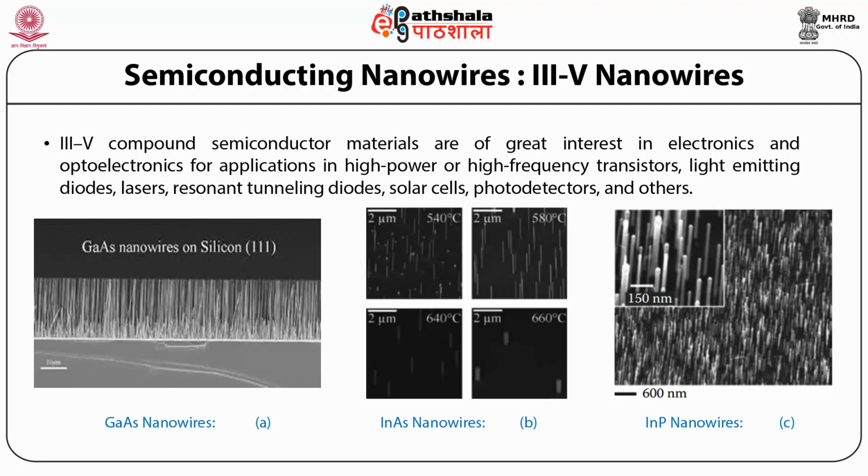It has been grown in the form of nanowire using laser assisted growth, sublimation of indium phosphide powder, molecular beam epitaxy method, and MOCVD, etc. Figure C shows the results of indium phosphide nanowire synthesized using MOCVD technique, which provides vertical uniform diameter nanowire.